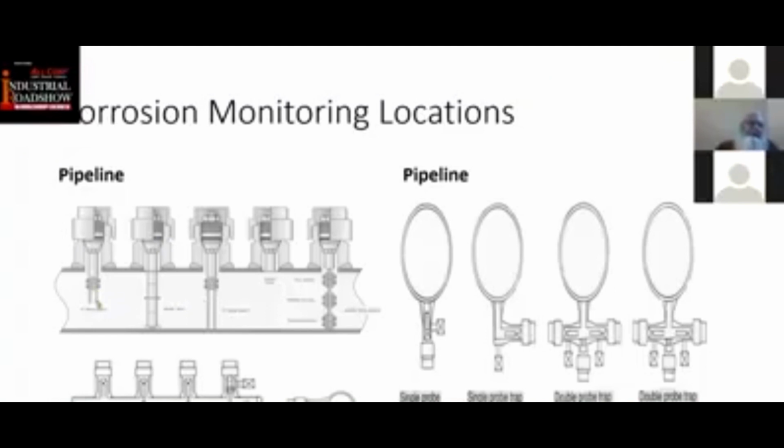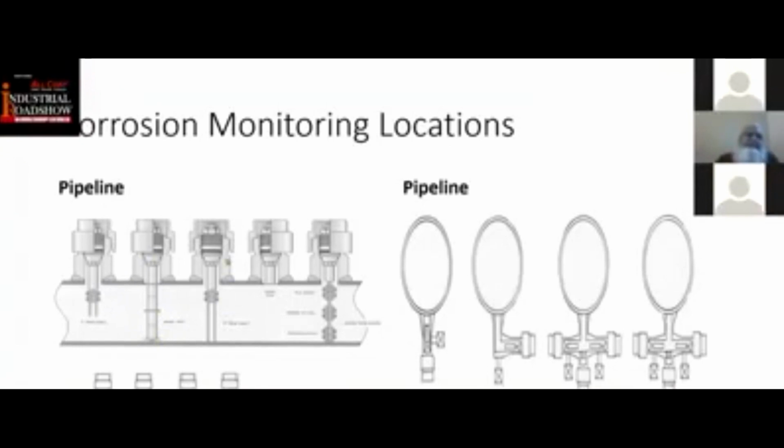This is a coupon, right, which is almost near the one surface of the wall. This is a disc coupon, which goes all the way down to the lower end of the pipeline. This is in fact also a coupon installation, which goes down to the end of the other line. This is a flush disc. In certain places where you have to use a pig on the lines, these techniques cannot be used because they require a free flow for the pig. In those cases, we prefer to use flush disc coupons, which do not obstruct the flow of the liquid.